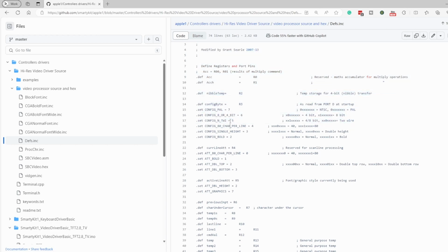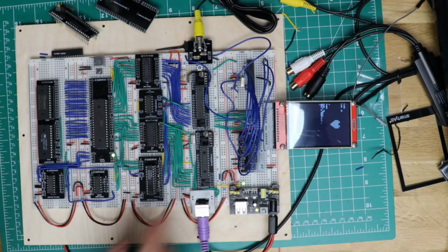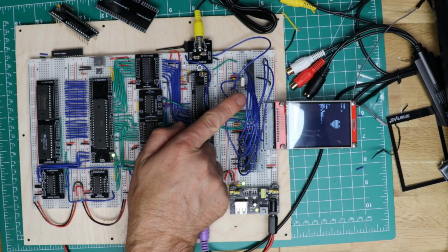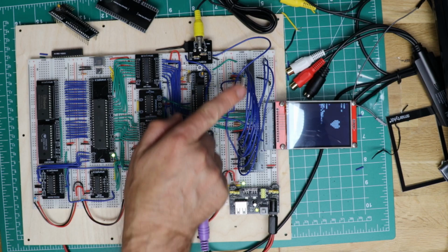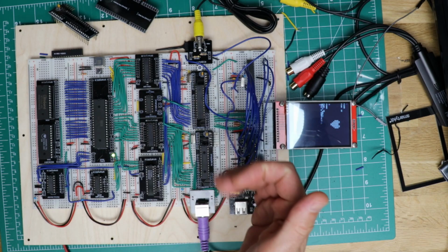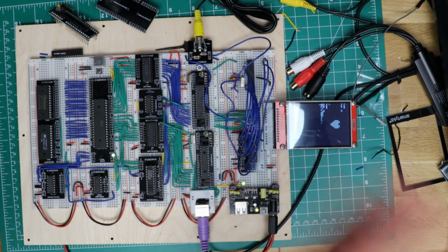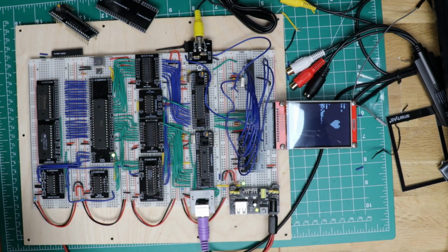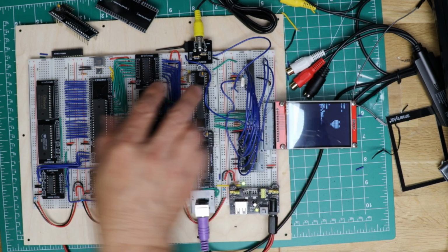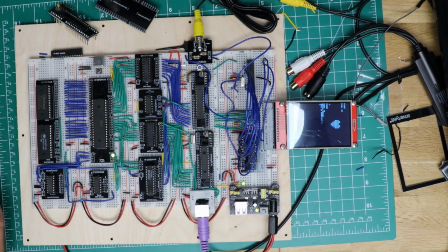What happens is that when this is booting up, it reads the data lines over here, sets them to input, has a read to see what's on there, and that is the config. Once it's got the config, it sets that to output and sends out. What was showing there is that the value for D5 over here was actually high rather than low.